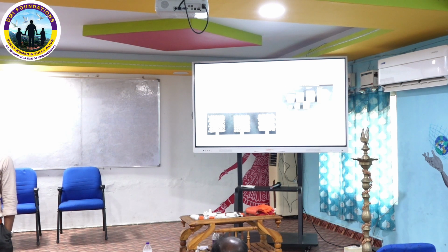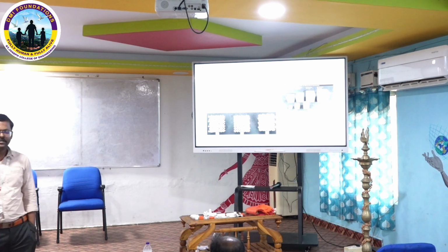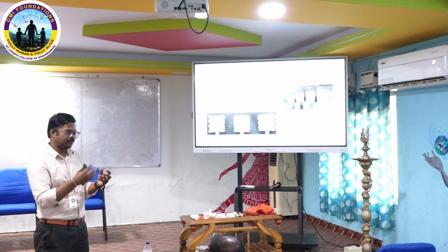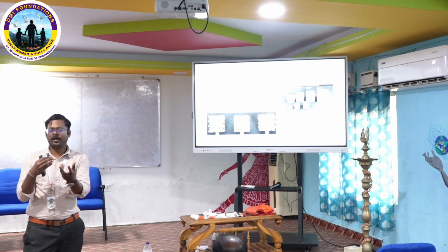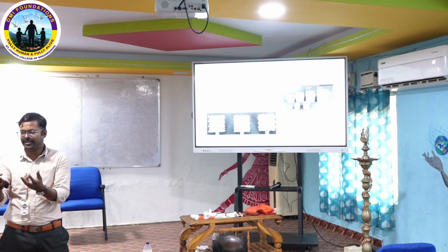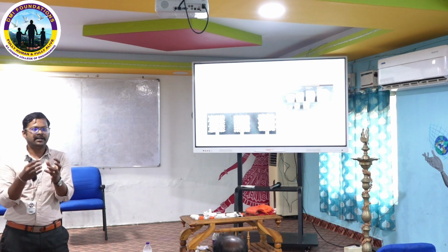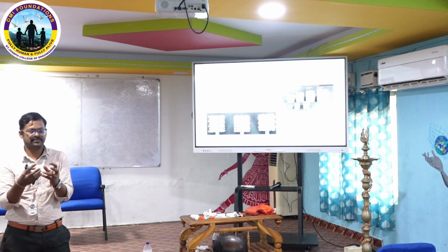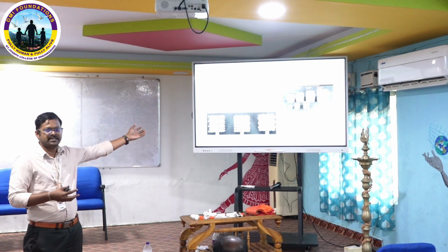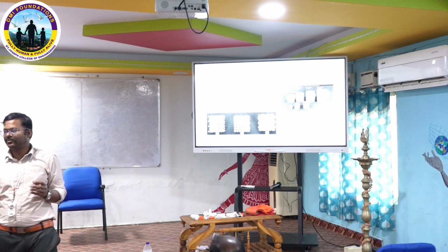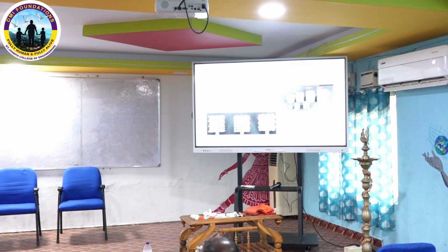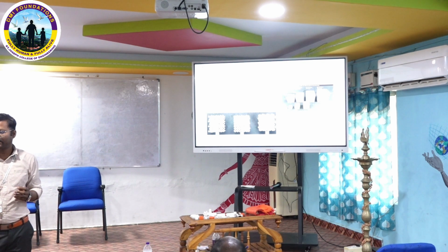That means above 30% of relative density, when you fabricate your parts, it may act as a solid structure. So what happens is, at the time of application, the response when a load is acting on the cube or any object, if you incorporate a 60 or 70% relative density lattice structure into that object, it acts as a solid structure. So for the structural properties of lattice structures, you can't get them at 70 or 80% relative density lattices. You need more energy absorption and stiffness.